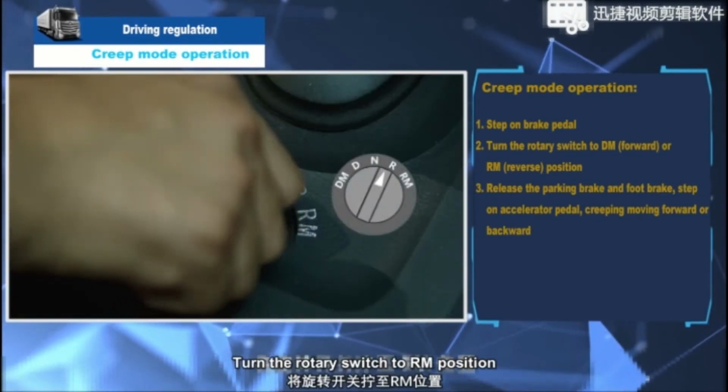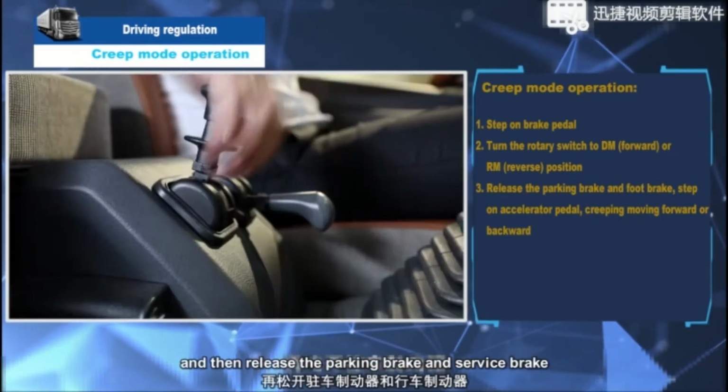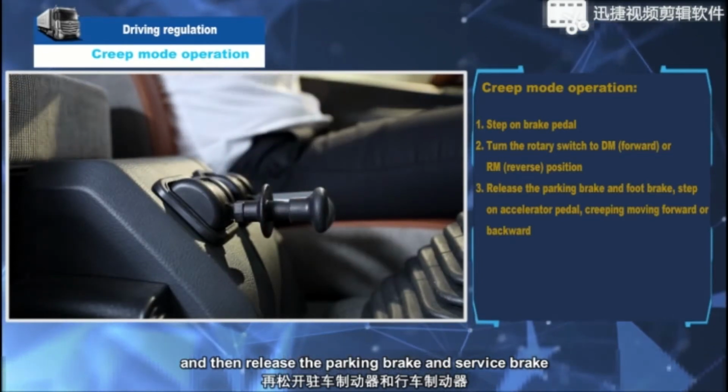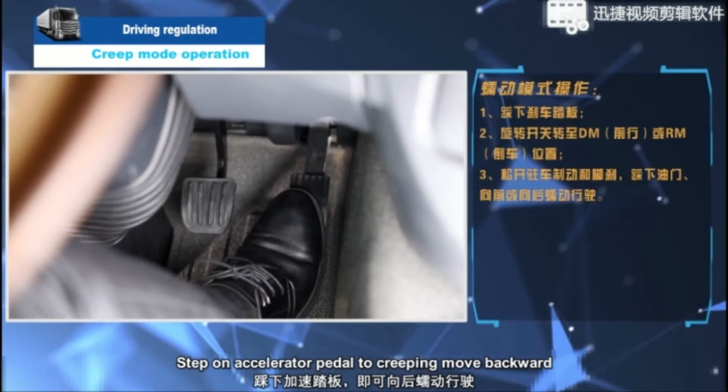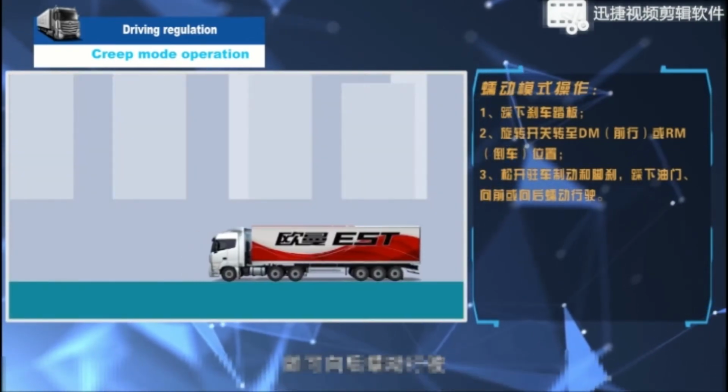Turn the rotary switch to iron position and then release the parking brake and service brake. Step on the accelerator pedal to creep forward.